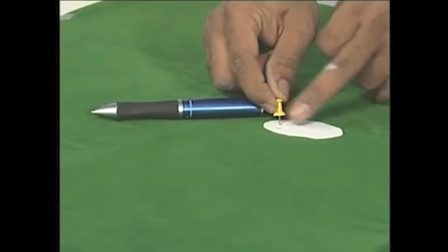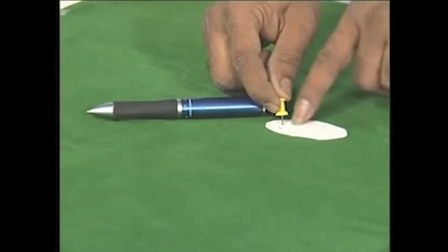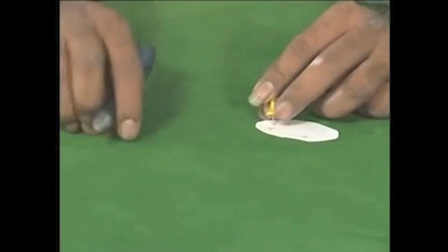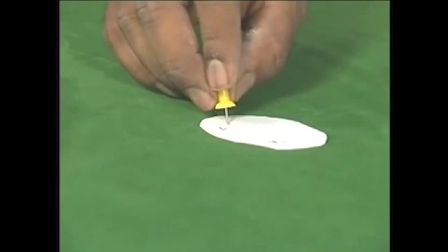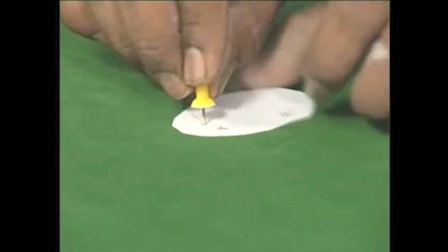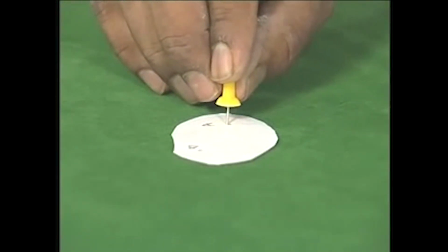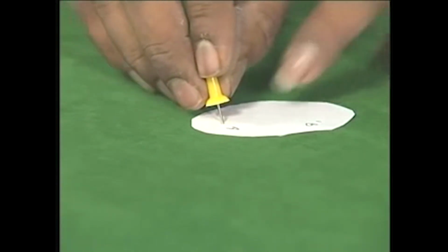The other distance that you have to take care of in order to know how much motion has occurred is a fixed point. The distance between that point and let us say another point that I choose over here does not change during this particular motion, okay. Or in other words, if I fix a point on the rigid body, the only way that it can move is by rotating, which means it reduces to one single degree of freedom that I have to define in order to understand the motion of this rigid body, okay. And mind you, this is all with respect to a point that I have fixed.